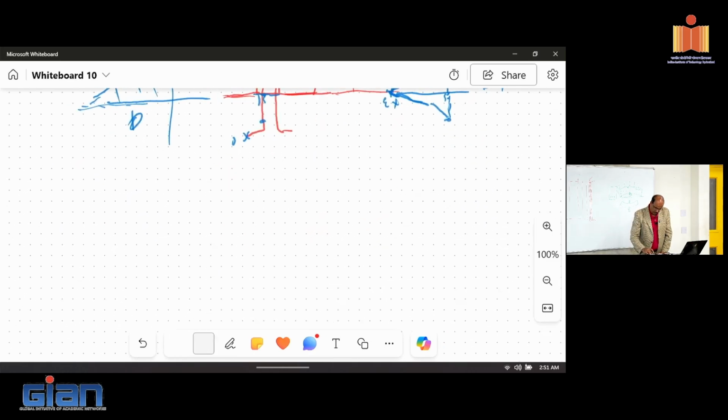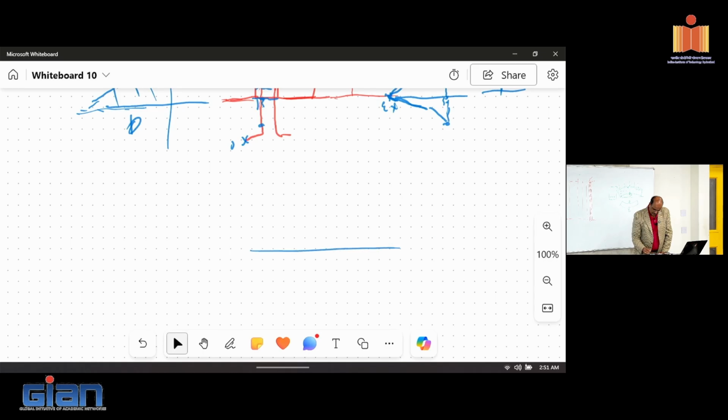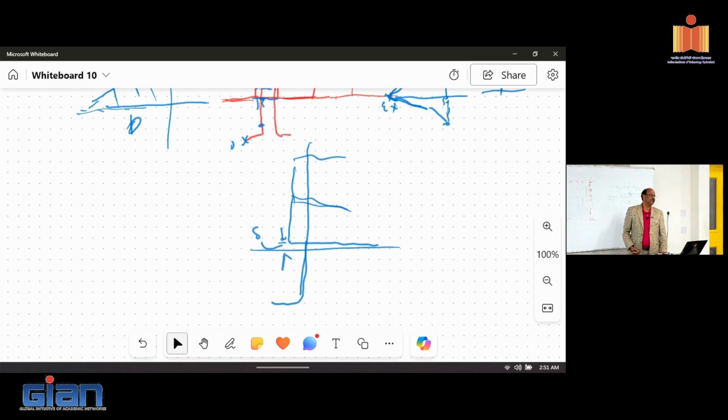So if I look a little more closely at the interface, here's your column, it is flexing, so there's a crack here at the base, the rebar is going into it. There will be a gap that opens up here, some delta. Because this rebar is not a pull out, it's not pulling out the rebar, it's basically going through the penetration effect and extending the rebar. So this delta, wherever the compression is, creates an angle here, some theta value.